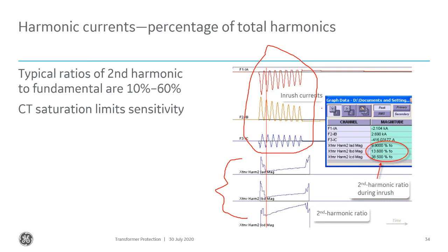So typically, the better value to set that at is average. Don't ever set that to per phase unless you want it to misoperate. The only reason that we give you per phase as a choice is because we're mimicking what is available in electromechanical relays. I don't think that's a good setting to give you, but nonetheless, that's the reason we do it, and that's the reason you shouldn't do it, right? You should not set that to per phase.